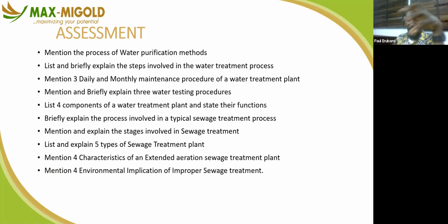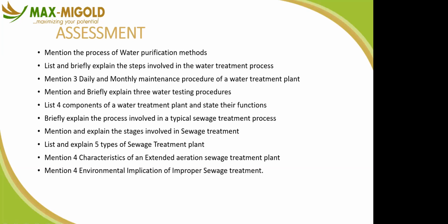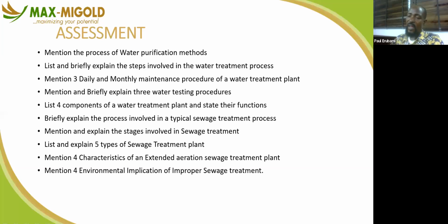Then after you have injected chemical and you still don't get much volume of water coming out, the next thing you do is look for a compressing machine. You compress the borehole. When you compress the borehole, the compressor works better than normal chemical. It will clean all the screen holes, and then you have a better yield of water. You have a better volume of water inside those columns. Then your submersible has enough water to take out. That is what is called compression of borehole. If you have never come across that kind of challenge before, you won't know it.